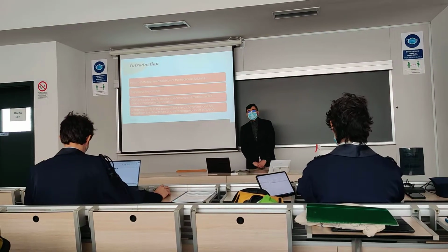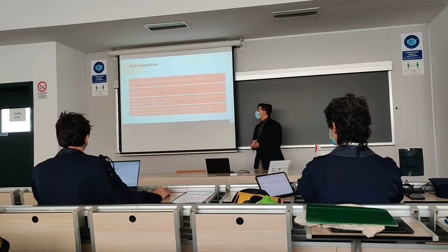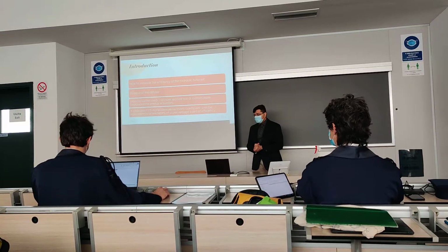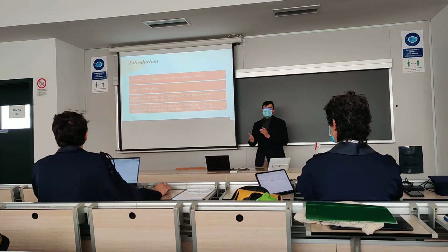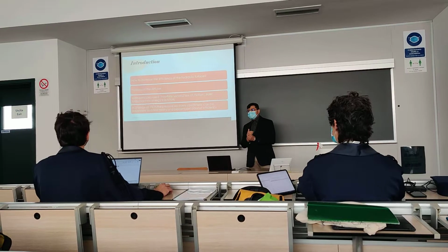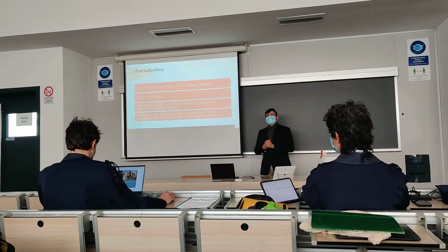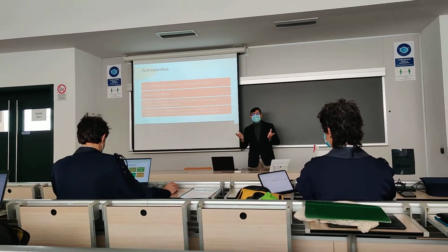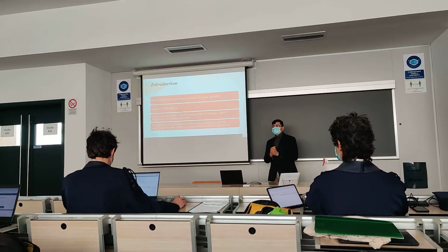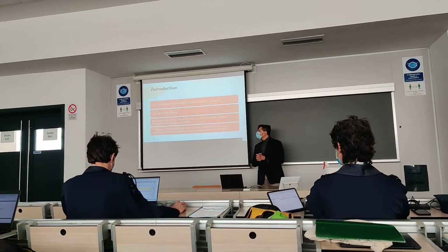So, as you all know, necessity is the mother of all inventions. There was a need that arose when fluid scientists were trying to increase the efficiency of hydraulic turbines. There was a debate going on whether the kinetic energy of the moving fluid from the blades can be converted to some useful work. So there comes the purpose of the diffuser. If you have the diffuser, we can utilize this kinetic energy of the fluid which has come out of the turbine, and if you keep it at the downstream, you can increase its efficiency.